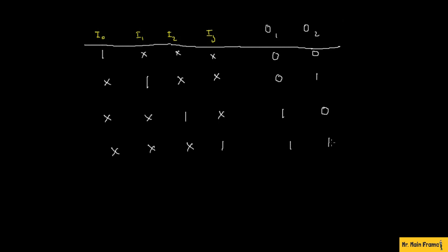So the difference between the other encoders and priority encoders is that when one of the lines is carrying data, the other lines will not be interrupting, right? You can see this from the truth table. If I0 is carrying data, you don't care what the other lines are carrying, so you can simply put don't care for the other lines, right?